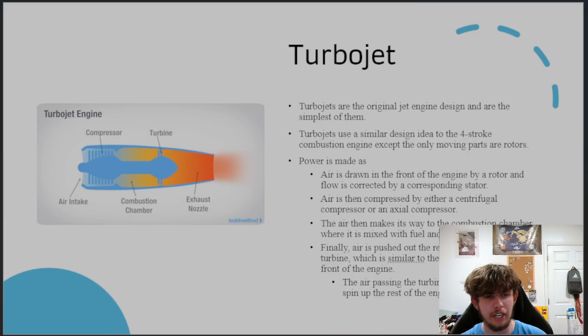In the combustion chamber of the engine, initially for startup, a spark plug is active to ignite the fuel-air mixture and help send it and pass it along. Once the engine is up to speed, however, there's enough heat generated in the combustion chamber that the spark plug's no longer needed. The engine itself is self-sustaining and generates its own combustion force.